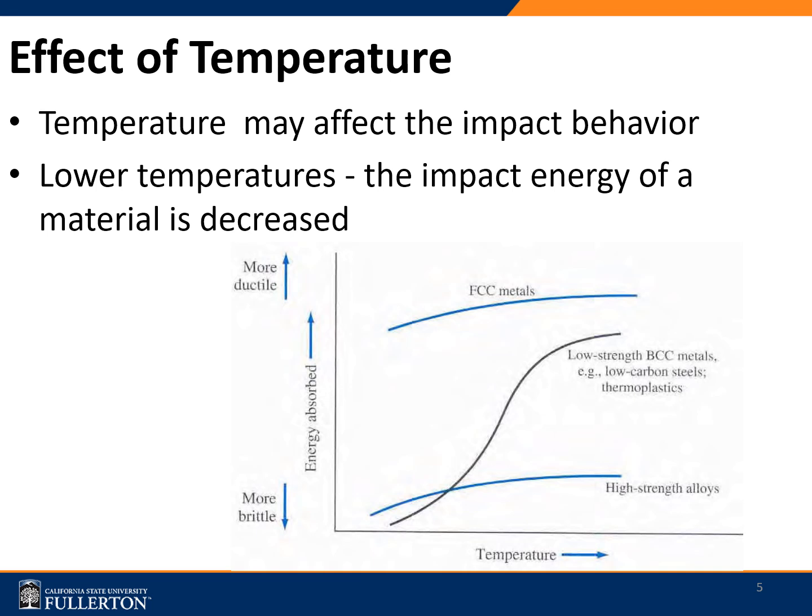We saw the example of a ship subject to extremely low temperatures in the deep sea, and that happened because the material's behavior would have changed from, let's say, more ductile at relatively high temperature to a more brittle state at very low temperatures, and the ship was subject to a catastrophic failure through brittle fracture.